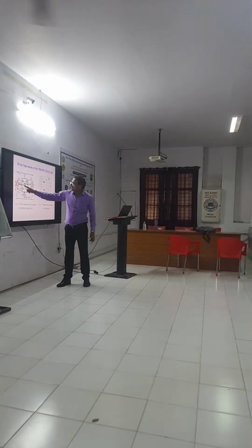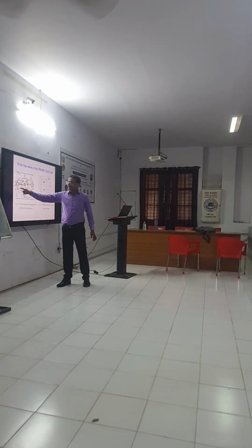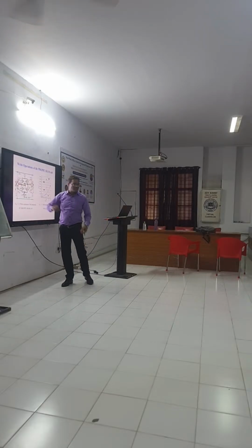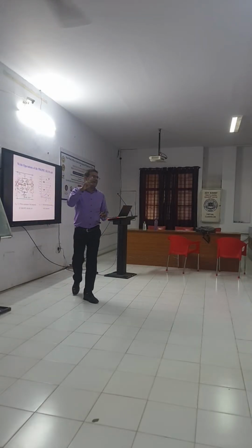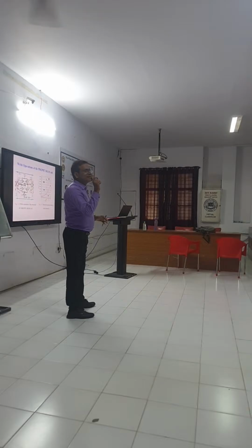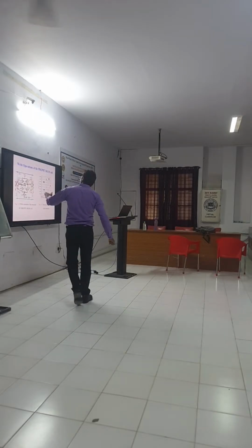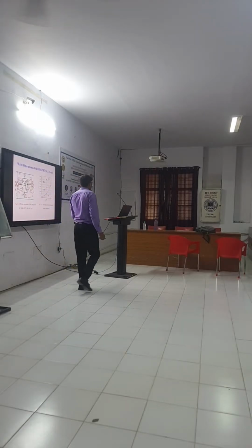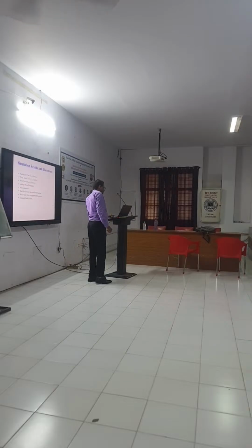Write operation, see, if here 0, if you are applying here 1, then current will flow through this and it starts rising, and if here is high and you are applying 0, this will start discharging. So the parallel path will discharge very fast. So this H node starts falling and this L node starts rising. When L has risen by 90%, that is the time taken to rise 90%, or the falling 90% of the H node, that is termed the write delay time. Get it?